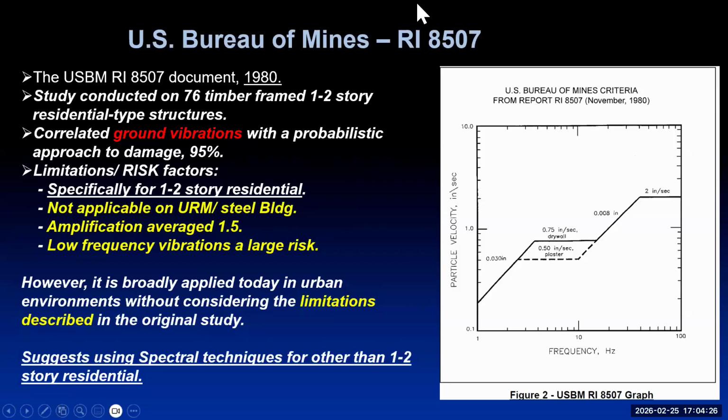But if you go into RI 8507 and you look at it in detail, they did the dynamic response. They measured the dynamic response to production blasting for coal. And they used spectral techniques like Dr. Geary just talked about, looking at the frequency and damping, measuring at ground level and above at the top to get the response of the structure.